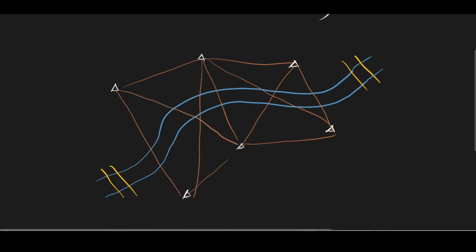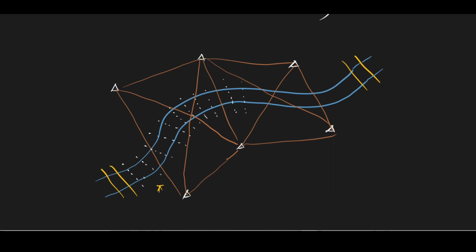Okay, so I have it right here. Now, once you've established your control points, you've observed them and then you've adjusted them, right? So you can now start traversing and get the points on the river. Okay. So one method to do that is to do cross sections of the river here, and then you observe the XYZ positions of these cross sections, and then for the points in between the cross sections, you can just interpolate that. Okay. So that's what you do.